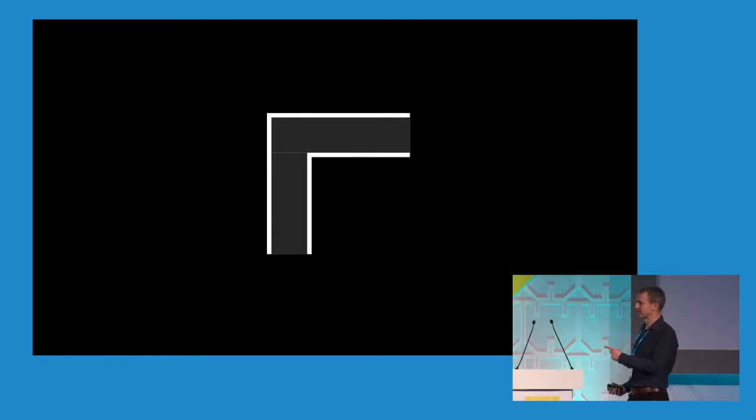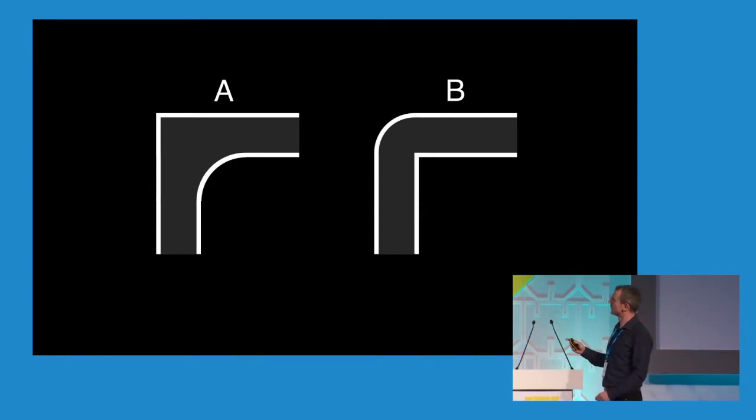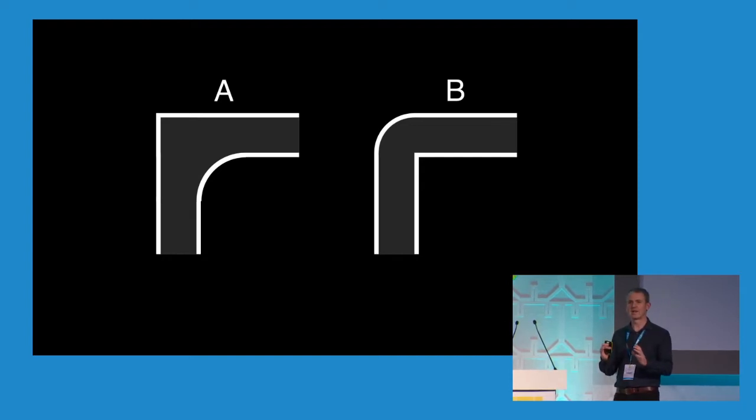You can probably also imagine that that's not great for turning flow around a corner, hard edges. But sometimes we have to make a bit of a compromise, whether that's for manufacturing reasons or anything else. And often we're left with having to decide whether we put a radius on the inside or the outside of that bend. Now, I'm not going to ask for a show of hands, but I think it's interesting to try and work out between the two of them which one's going to be better or not. One of the rules that we follow generally with managing flow is to try and keep the cross-sectional area the same.